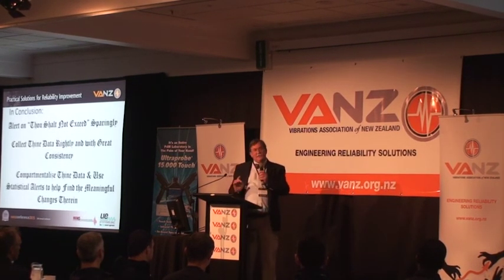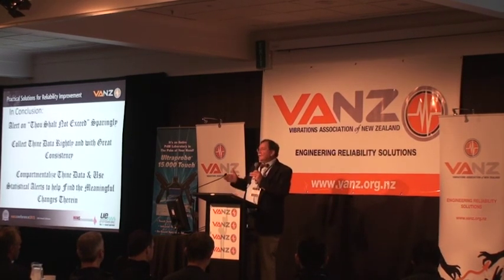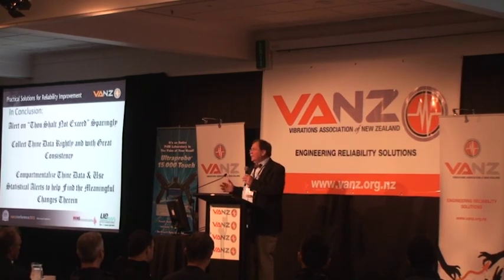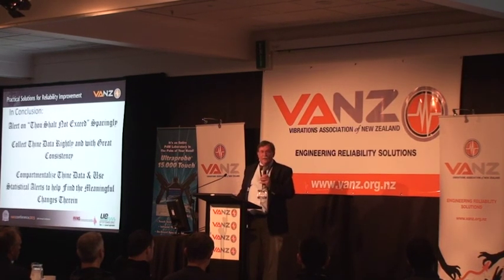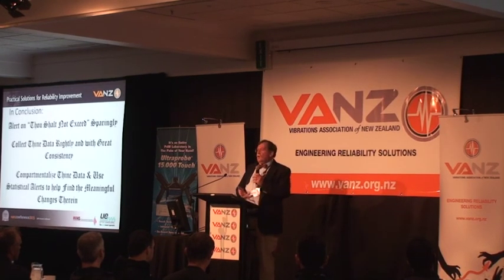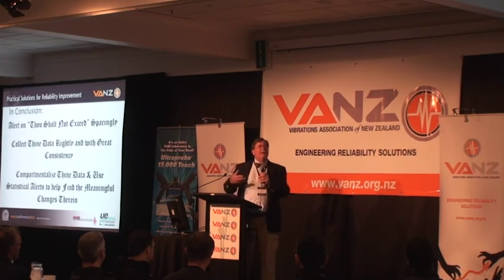And so what they did for the short term, because they didn't have time to get a whole new set of blades, they literally pulled the fourth stage out of all three of the low pressure turbines on both sides and put blanking plates in there because that got us back online. We were, I would say, 5 or 6% reduced on our power, but at least that gave the opportunity to have new blades remachined. But it turned out to be a problem.